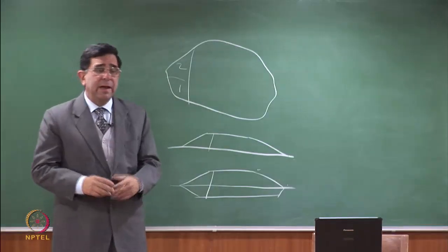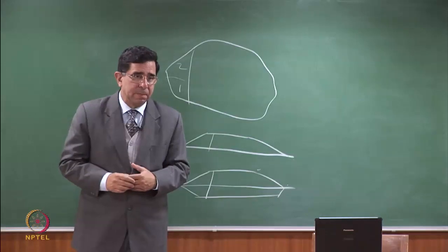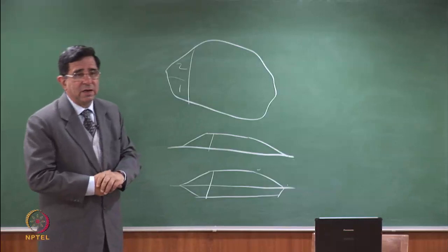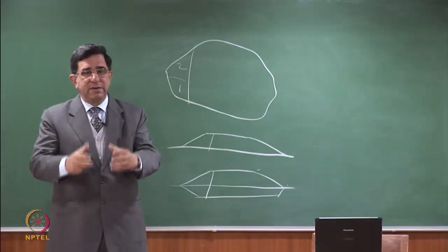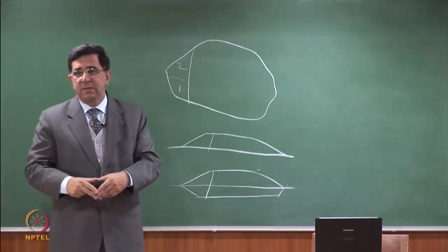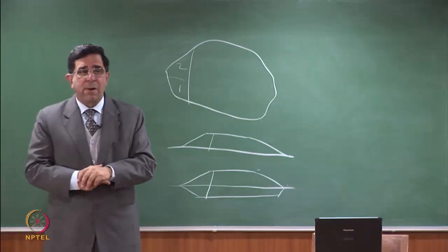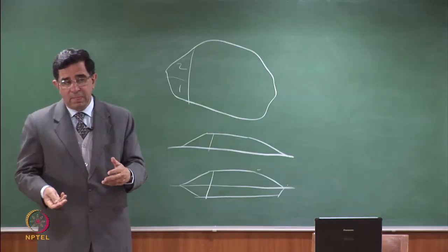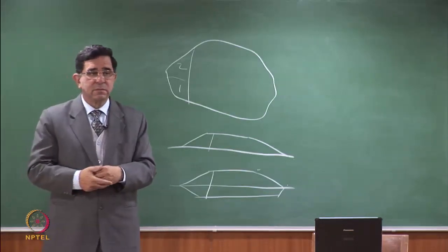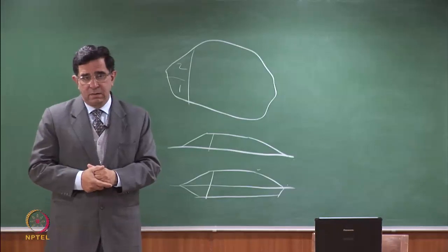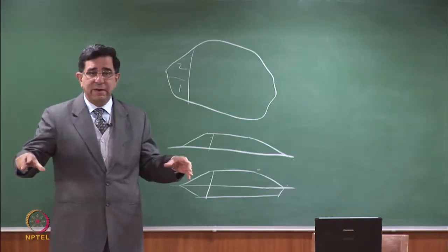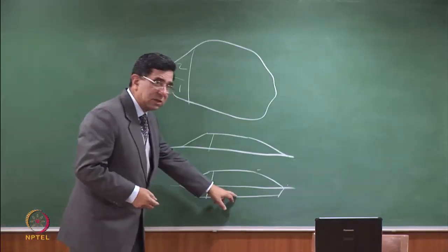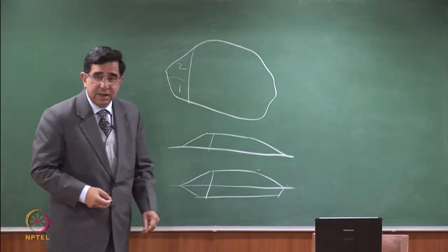I'd like to now put my leachate collection wells. Okay. So let us say in phase 1, where will you put your leachate collection well? Is it at the center of the phase? Is it at the side of the phase? Why to the side? Why not to the center? We take all the leachate to the sides. We don't keep leachate at the center of a landfill. I will not be taking all my leachate here. I'll be taking all my leachate here.